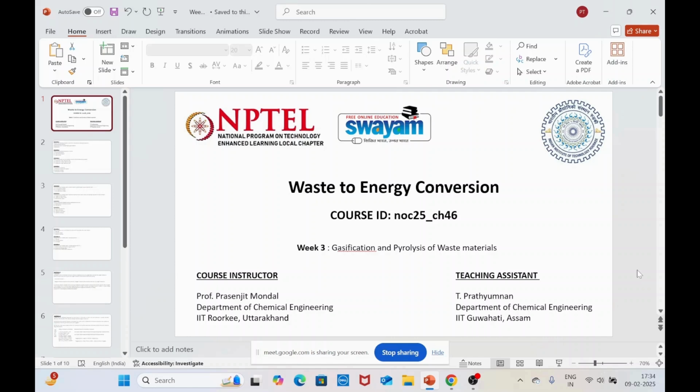Syngas usually contains acidic gases, so that needs to be cleaned. You have acidic gases like CO2 and H2S. Those need to be concentrated, and then we can obtain CO2 as well as H2S, and from there we can obtain the sulfur. Again, for this process there are multiple types of adsorption processes used. Let's discuss that when we go to the assignment solving section.